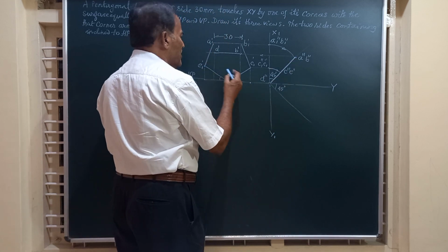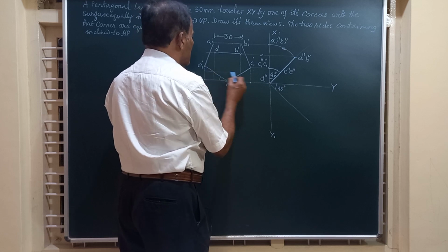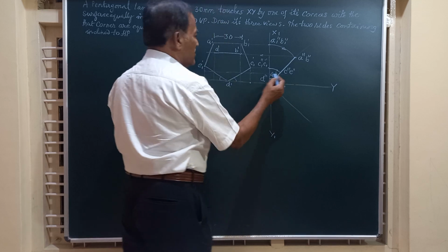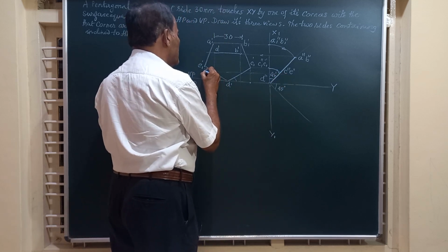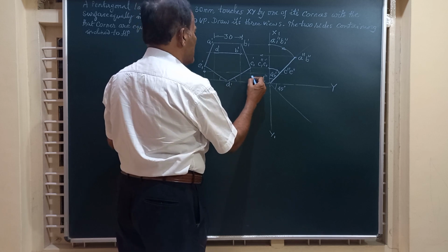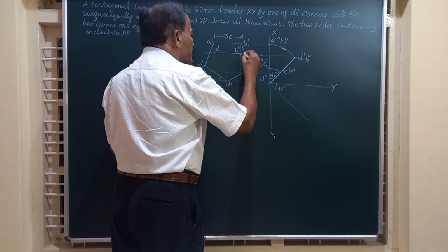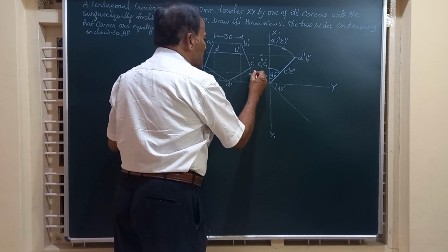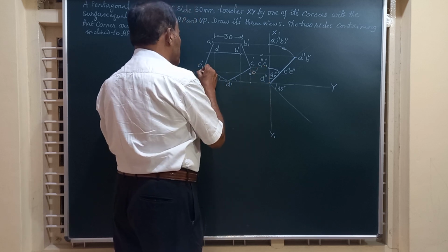So that point we are going to transfer to the corresponding points in the front view. So friends, I can write down a line from there and transfer that to here. So this E is going to come here, and this point C will come here. I will show this in a different color. So this is the final C dash, and this is E dash.